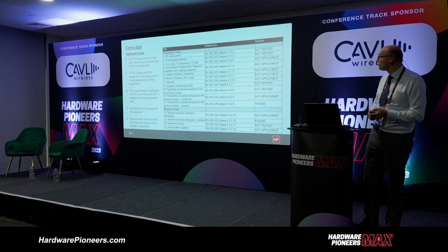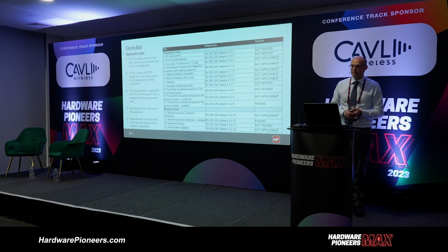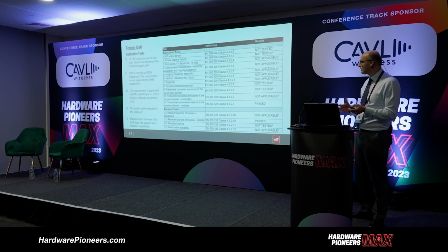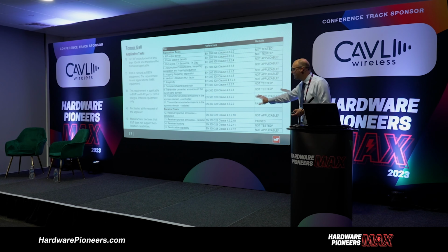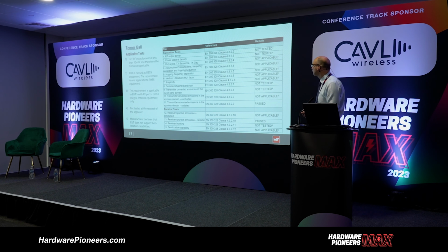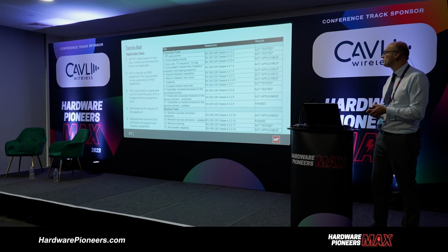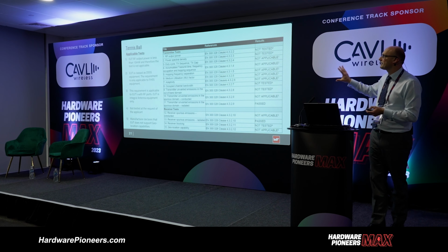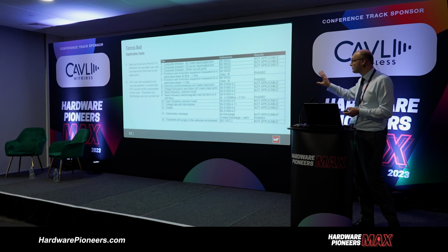And here is an example of the typical tests that would be applied to a radio product. Now, if I've designed that radio product from scratch and used discrete components, I would need to meet all these particular clauses to meet those essential requirements. Because I'm using a pre-approved module, out of these 15 tests, we've only had to reassess 2 of those. So the speed of access to the market is a lot quicker by using these pre-approved modules, provided that the module manufacturer has done their testing diligently and used the correct harmonized standards. Once again, you should be able to identify that from the DoC.